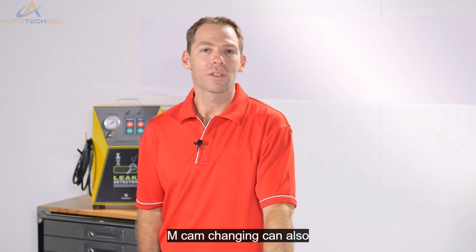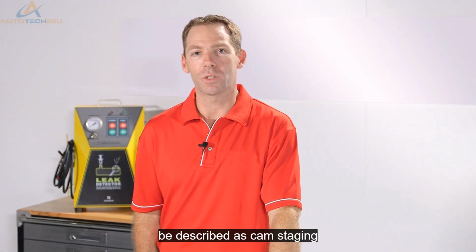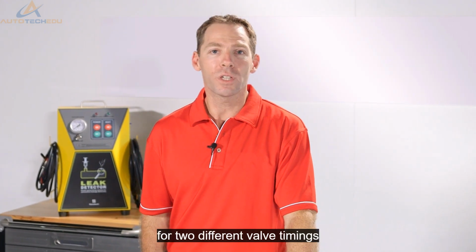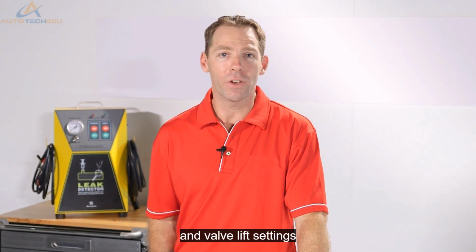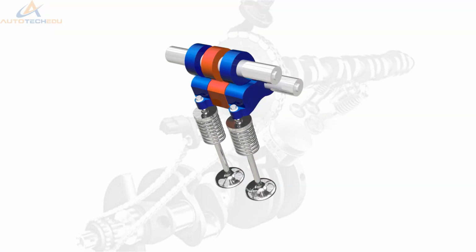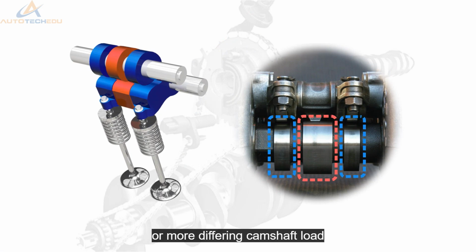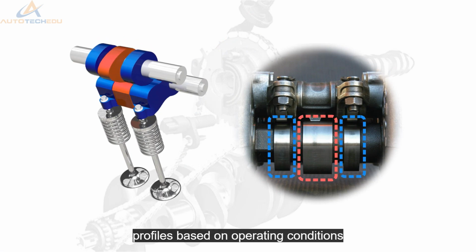Cam changing can also be described as cam staging. Most stage systems allow for two different valve timings and valve lift settings. These systems switch between two or more differing camshaft load profiles based on operating conditions.